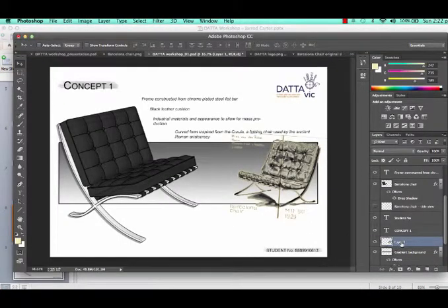And we can do that through opacity. So actually, first, let's rename the layer. And in the layer tree, if you select your layer, up here you'll see a feature called opacity, which we've seen in a few of the tools today. Move that down to about 50%.